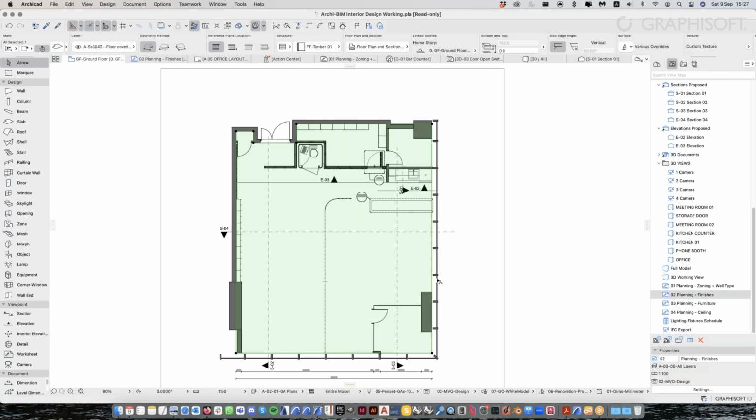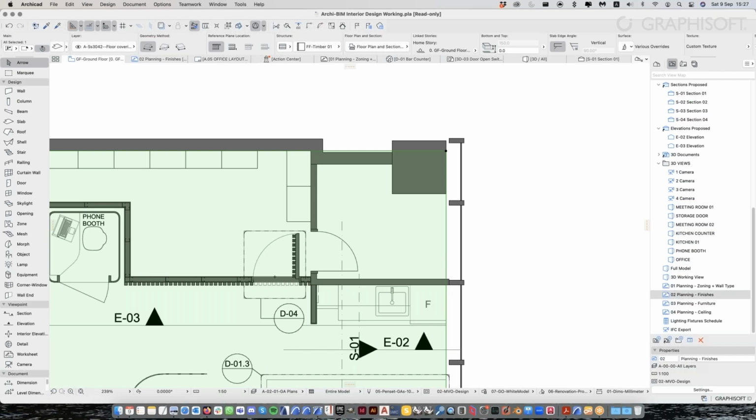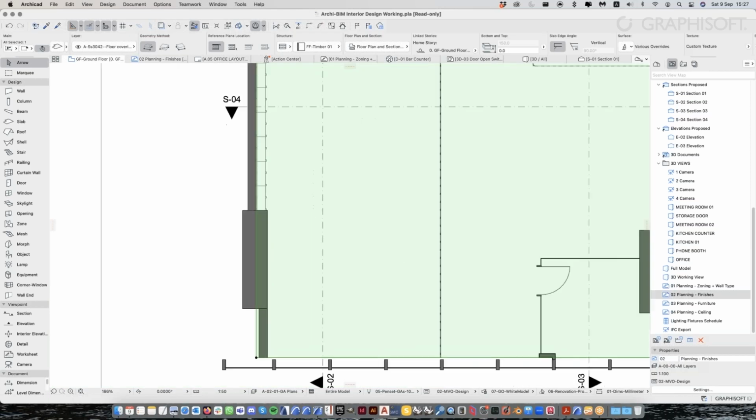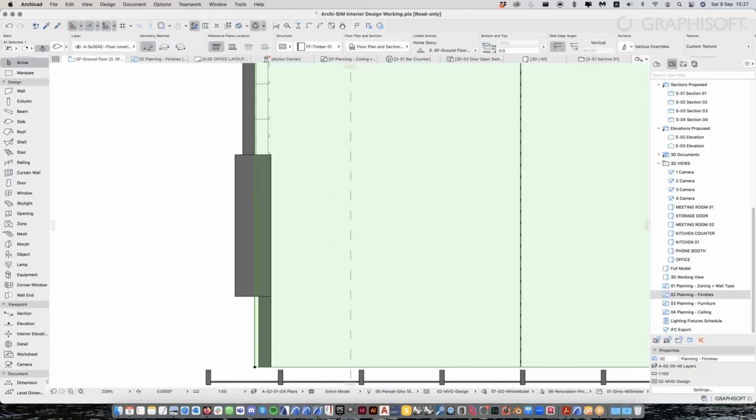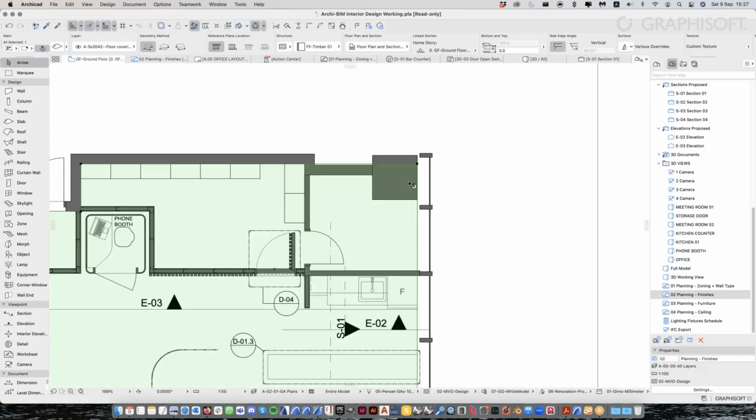But of course, two things. One is I don't want this piece here, right? This should be the wall, and then I remove it for the tiles. And also, I don't want it here. Doesn't make sense. It should be out of the boundary of the space. So what can I do? This time, I can maybe click on the node and have the pet palette shown. And this time, I'm going to use a tool called Subtract from Polygon. Actually, this tool is available even if you click on the edge. Okay, it's this, Subtract from Polygon.